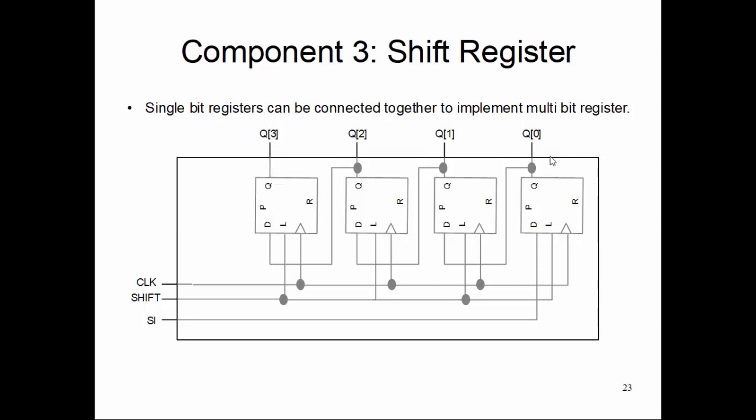But the basic concept is that you are now connecting registers in a daisy chain fashion to selectively shift the incoming bit pattern through, one input bit at a time.